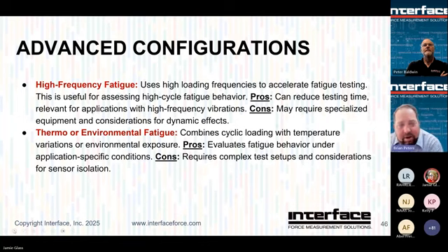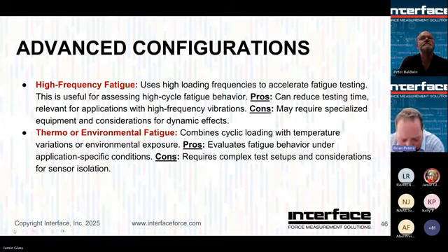Thermal and or environmental fatigue testing. So it's real common, especially with some of the material test frames, to have environmental chambers around your test article. Makes sense. You may need to test at a high temperature, may need to test in a corrosive environment. That's fine. Just do everything you can to get the sensors outside of that, right? And keep them isolated. Now, even if the load cell is outside of the thermal chamber, what kind of temperature are you seeing propagate through the load string, right? That's something else to keep in mind.